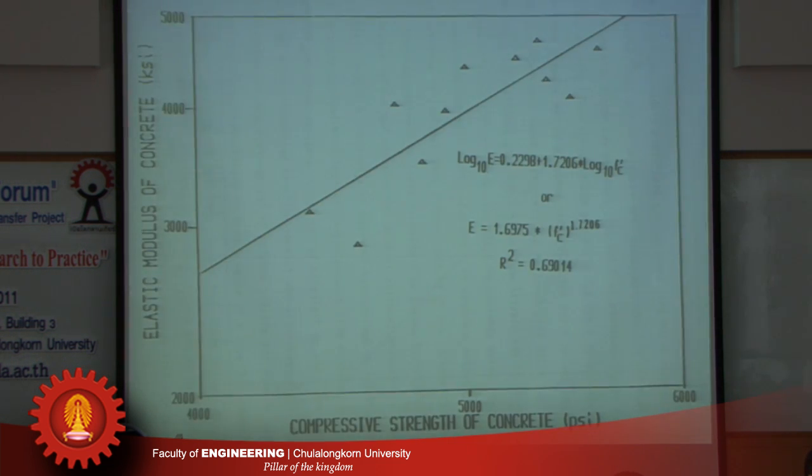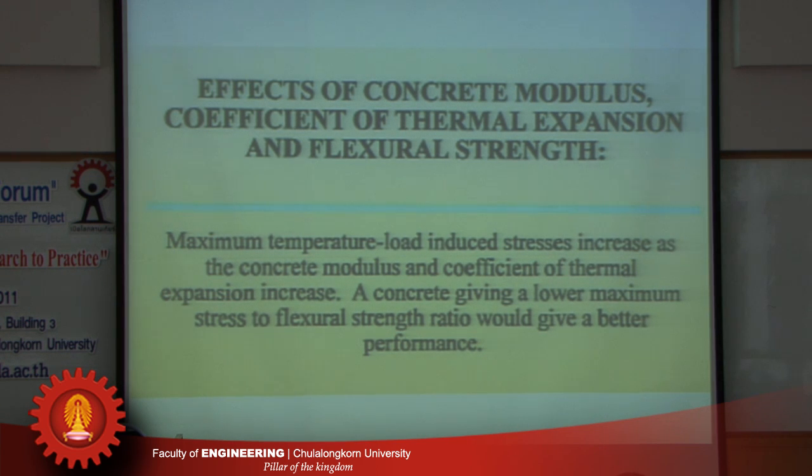Okay, usually we show that the elastic modulus is related to the strength. In this case, we didn't have the flexural strength, so we plotted against the compressive strength. So it shows that the stronger concrete actually cracks more. In this particular case, I'm not saying that it will always crack more. It depends on the situation, so we have to do an analysis.